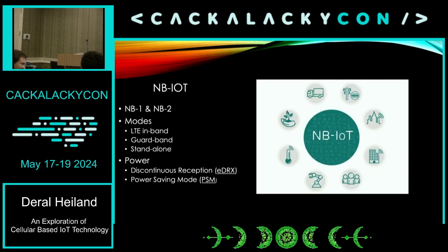Real quick on NB-IoT, this functions in several different modes. You have LTE in-band, where communication goes in the actual LTE bands. You have guard band: when you look at the channels or bands in the LTE signal range, there are gaps between them, so a device can communicate in between those two bands. It's known as the guard band area. And then you get standalone, which for the most part utilizes the earlier standards, and it's usually focused on specific functions and services.